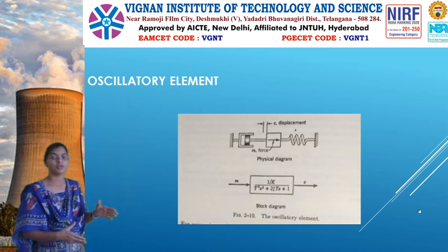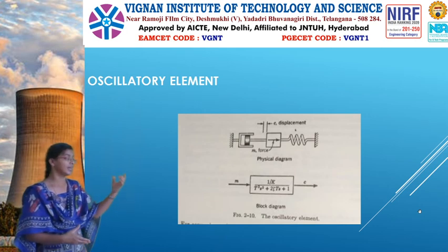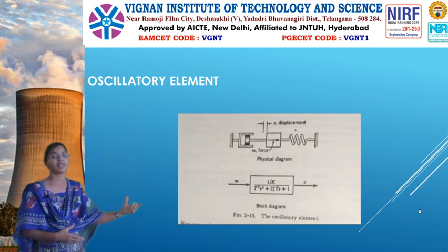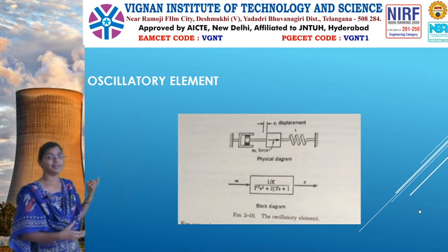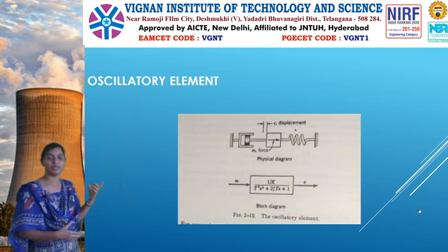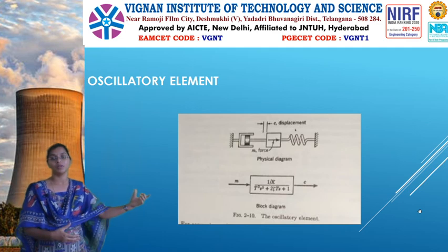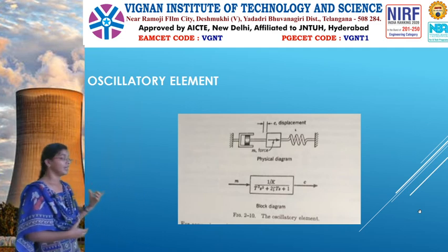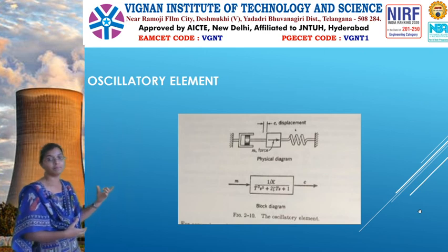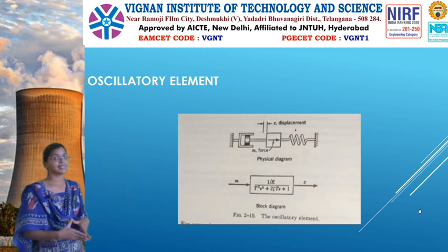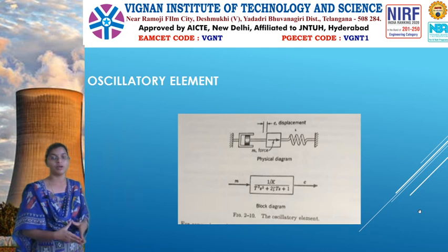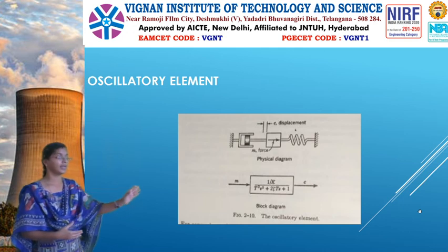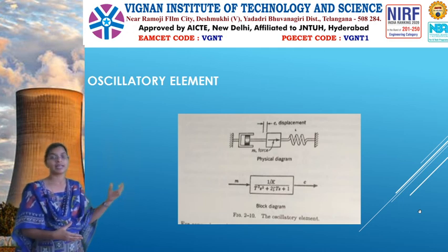So if we write that second order system equation in a single block, in process industries the input is a flow rate. Here we are taking a liquid process. That entire system has an input of M, which is a flow rate, and the output is the head of a particular tank. You are applying the input here and getting the output there. So this is a second order system.